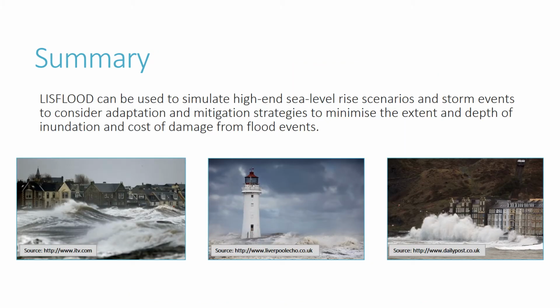Coastal zones worldwide are at risk of flood inundation as a result of sea level rise and extreme conditions such as storm surges and wave overtopping. There is a need to plan for, adapt to and mitigate against such risks. Coastal inundation models can help with this. LISFLOOD is a two-dimensional flood inundation model which can be used to simulate water depth and extent in coastal, estuarine and fluvial environments under a range of tidal and meteorological conditions.